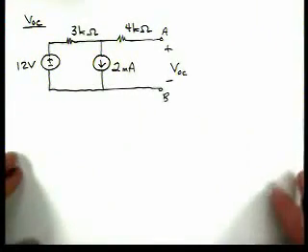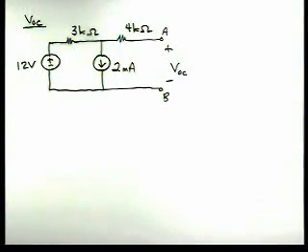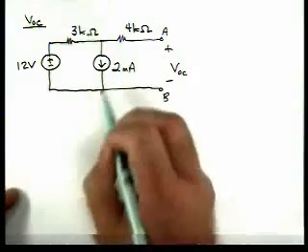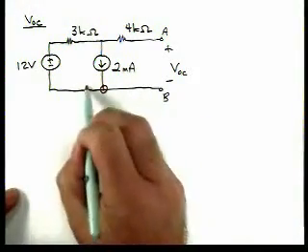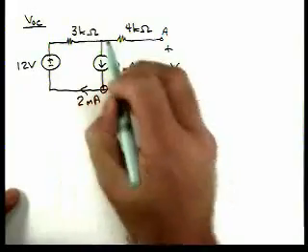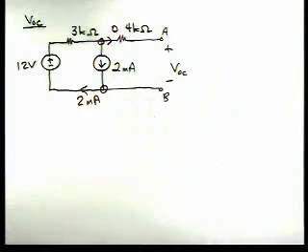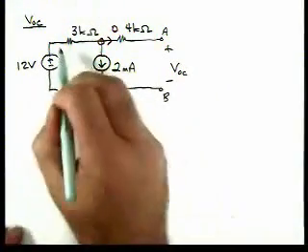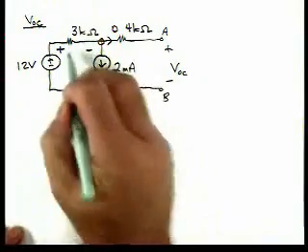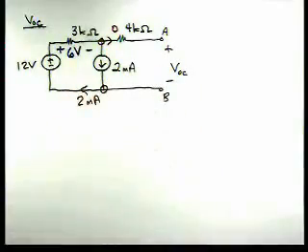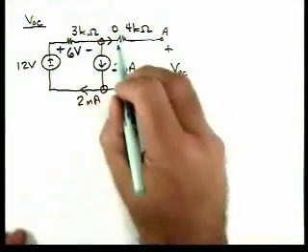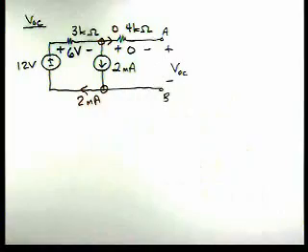When we remove the 2 kilo ohm resistor, here's our circuit now, and we're going to find the open circuit voltage. If we apply Kirchhoff's current law here, there's 2 milliamps flowing there and 0 out there. So the voltage across this resistor is 6 volts: 2 milliamps times 3K. The voltage across this resistor is 0 because the current's 0.